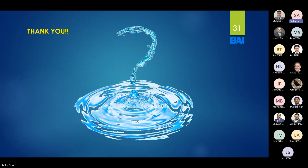You touched a little bit on the geomorphology of the stream. Natural channels are always shifting, sometimes to the left side or right side. So it is not necessarily true that the abutment scour value which we have computed is correct. Probably the contraction scour may be used where we have the abutment scour value, so maybe it is higher than the abutment scour value.